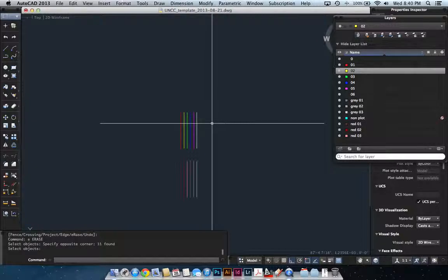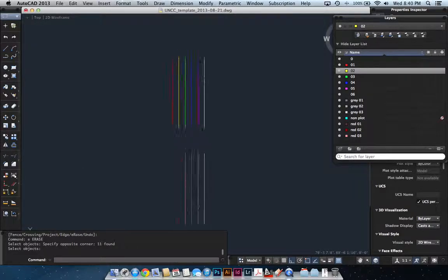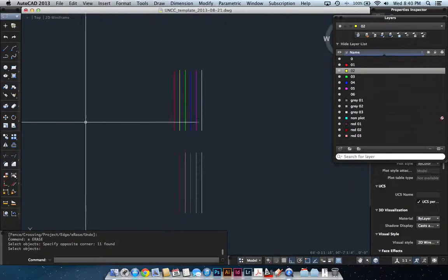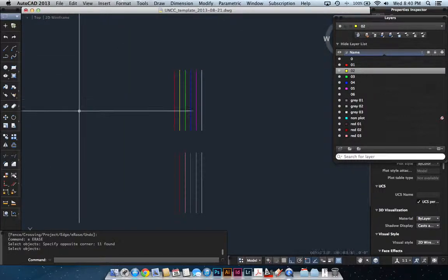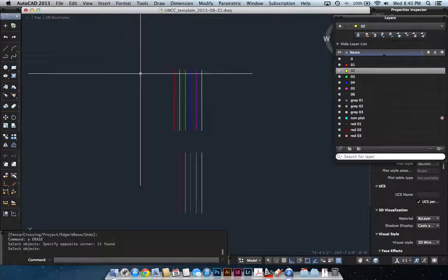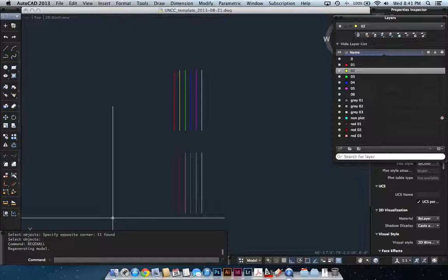elements with the drawing. The only other thing I wanted to say is in case you ever get artifacting, which I can't really create in this tutorial, but artifacting meaning you see some ghosted objects here or your curves start to become polylines and lose some of their refinement, you can use a command called regen all. And you see how it's typed in R-E-G-E-N-A-L-L, regen all.